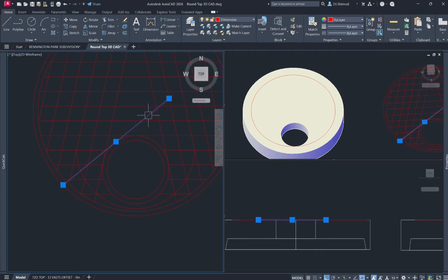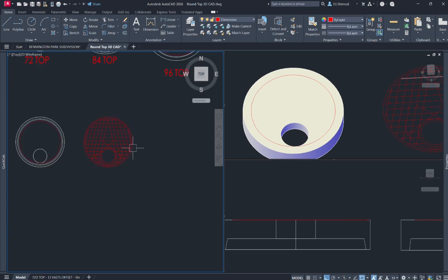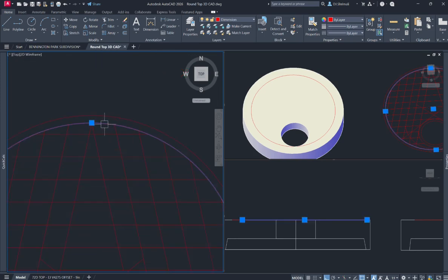So you can either do the band bars or the diagonal bars, but here we don't have a lot of space to put the diagonal bars, so we are just doing the band bar along with the 2 diagonal bars. Okay, so that way we are covering, or reinforcing, the opening.